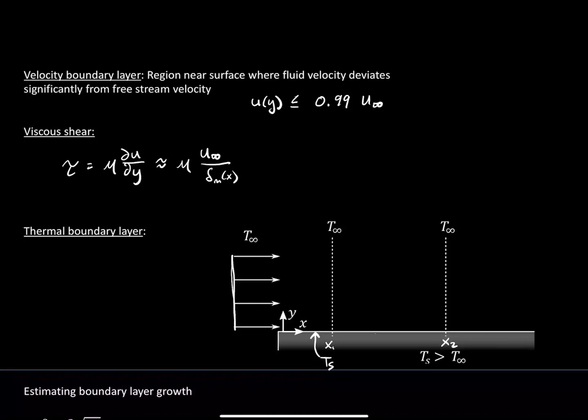What you end up with is once the fluid hits this plate, the fluid right at the edge of the plate will immediately become Ts. Right? It becomes Ts. It's held at that temperature. But then you get this thermal wave that propagates. And it's really very similar to the 1D transient cases where you have this thermal wave propagating as a function of time. Now it's this thermal wave propagating as a function of the duration over which the fluid has been exposed to this plate.